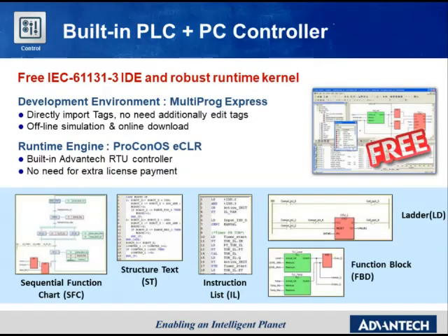In the PLC system structure, there are two important terms: IDE, Integrated Development Environment, and RTE, Real-Time Environment, also called Runtime Engine. IDE is software that could be installed on a PC or notebook to develop the project in your office. In ADAM3600, the IDE software we use is called Multiprog Express.